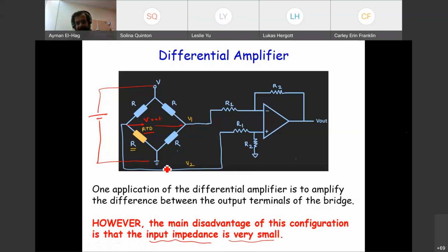So for example, in this circuit, this is your V2 and this is your V1. The input impedance is the impedance that your input can see. Now we know that I equals 0, so it is like it is disconnected. No current can enter inside, because here you have an infinite resistance. So the resistance that we have will be R1 plus R2. This is your input impedance.